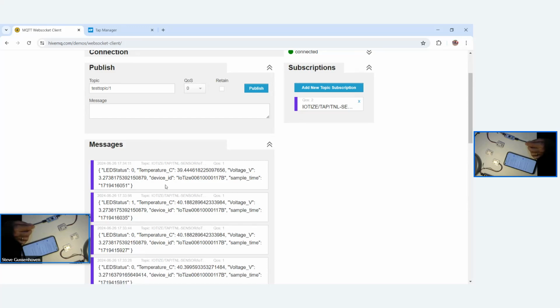Keep in mind, this is also a bidirectional communication. So we can also publish messages to our MQTT topics if we had writable variables. In this case, I'm just treating this as readable. And we can actually subscribe, in a sense, to these MQTT feeds in order to capture data coming from my target board here. So I'm just going to switch back to our presentation here.